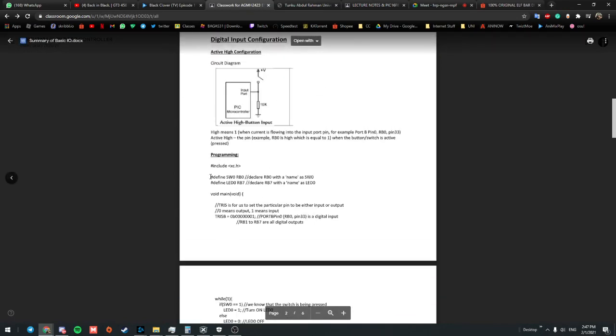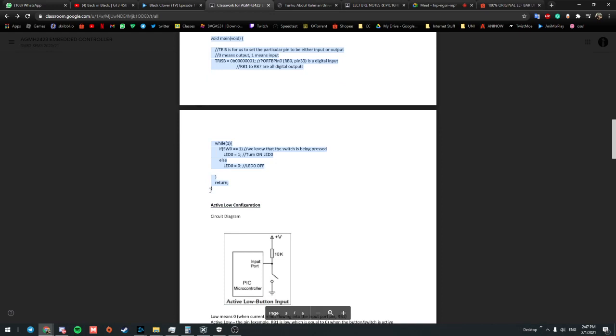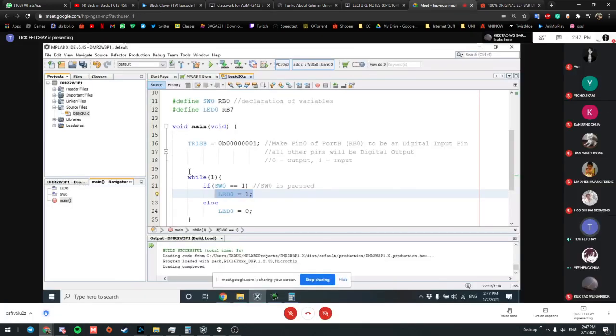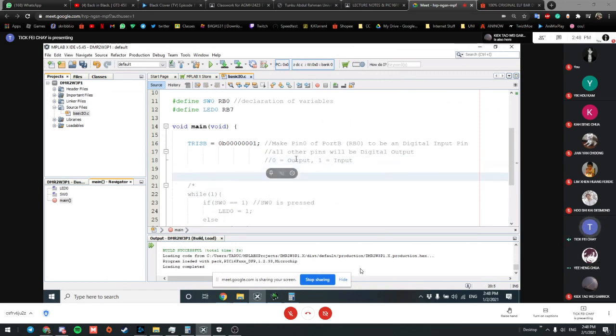Okay, you try this way. Are you having WA1? Now you comment your WA1. You use comment all, slash then asterisk then slash, right? You comment all the WA1. Then your TRISB, you make it all output. It means 0b, then all the pins are equal to 0.